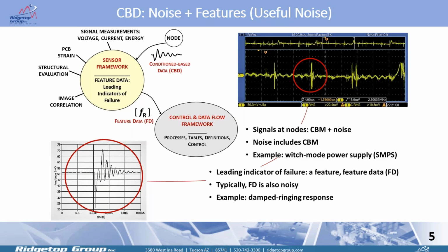You'll see that, for example, up there in the upper right corner is the output of a power supply. And you can see it consists of all kinds of signals. There is the DC voltage, there's some ripple voltage, there's some shot noise, there's some thermal noise, and there's some ringing responses. There's all kinds of data.